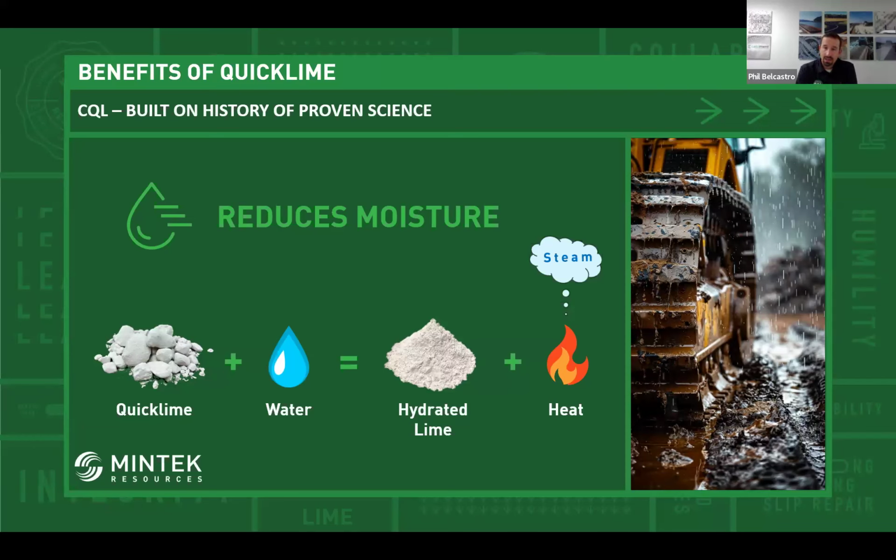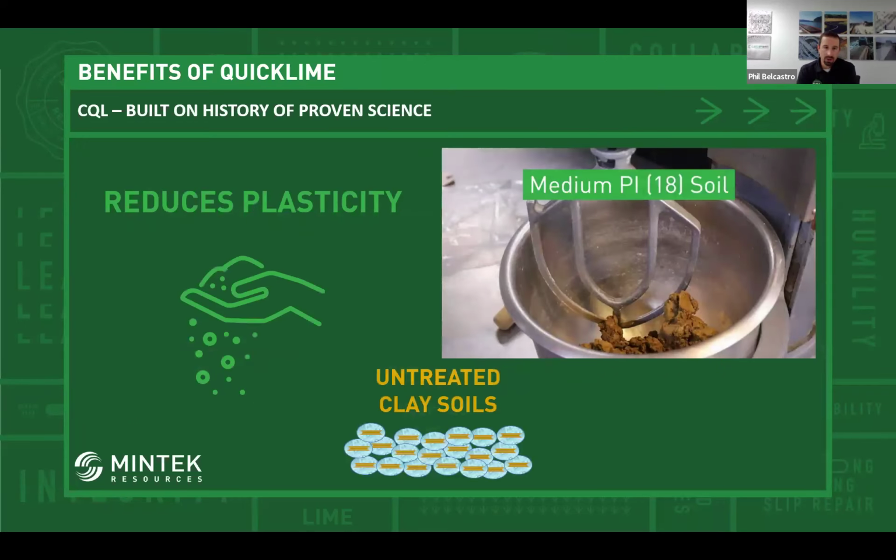So, hey, we're still calcium oxide, adding water, making calcium hydroxide. With the CQL though, now it's finer. Those reactions are going to be happening faster again. Maybe that's going to help us generate just that much more heat, and maybe that's going to help us drive off even more moisture, which could potentially lead to some lower rates. Now, maybe that's a 2.5% dose rate versus 3, but that extra 0.5% might help us add up over the site cost.